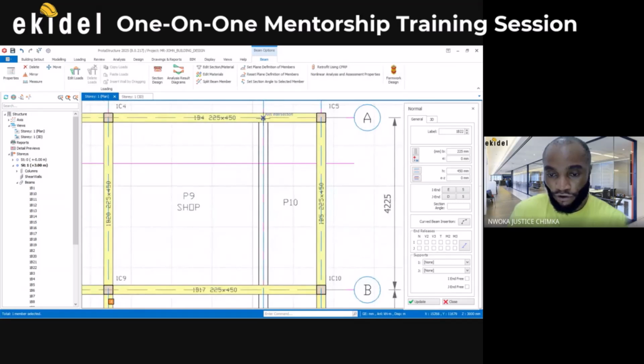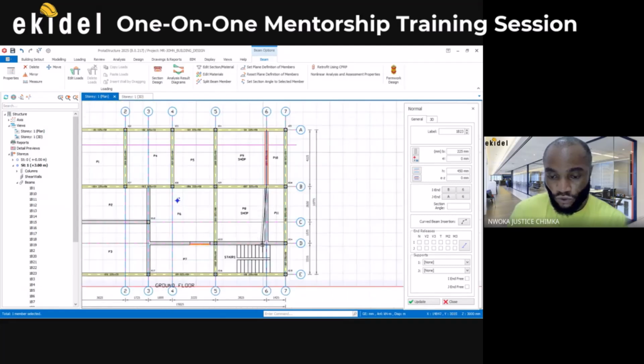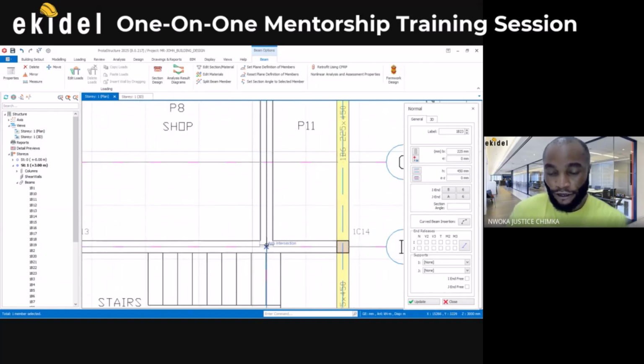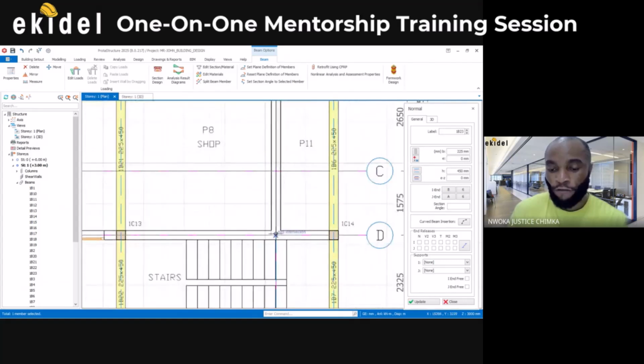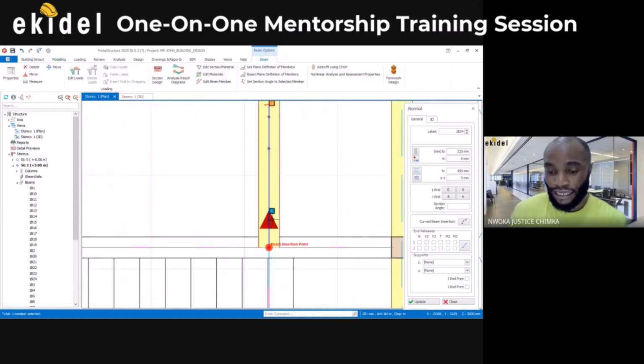This one is running from this beam to this beam, and then continue again from this beam to, okay, now note this. You can see that this beam here, which I'm about to insert now, will be carried by the beam that is going in this direction. Now, before I insert this beam, I must insert the main beam that will carry it. Else, it will be seen as if it is a free end, a cantilever end. Once you see this triangular sign, it means cantilever.